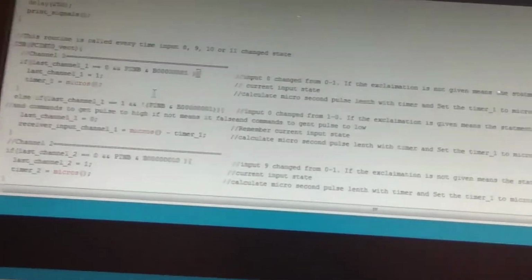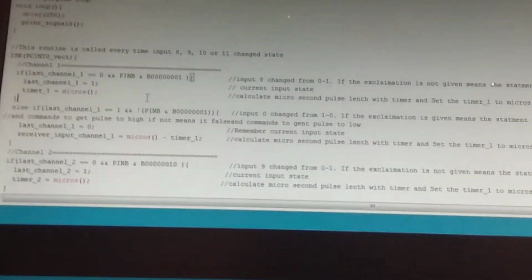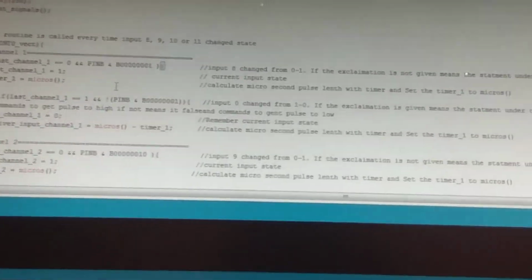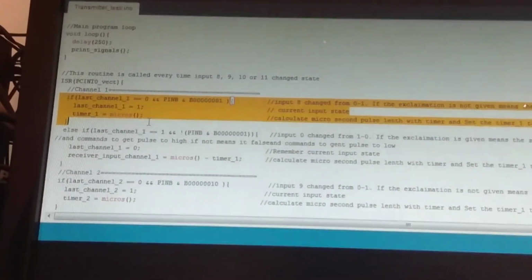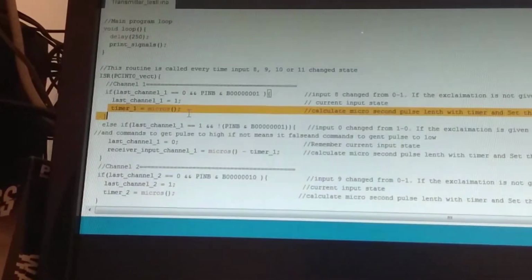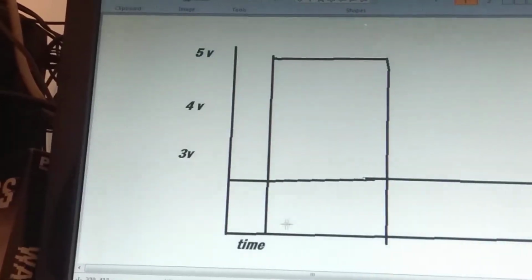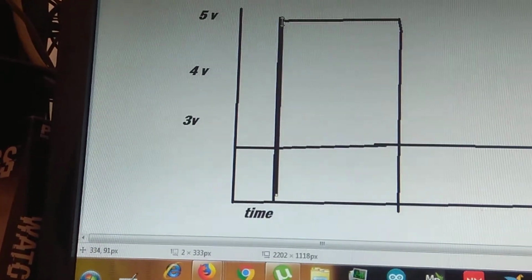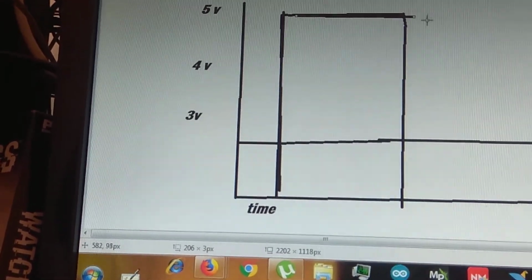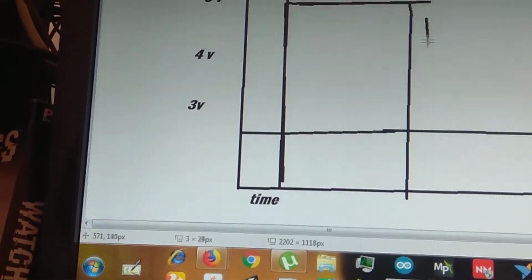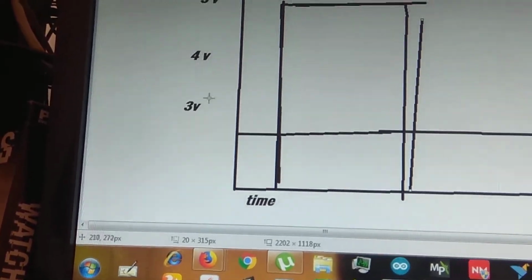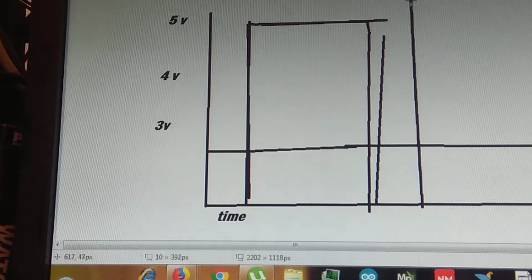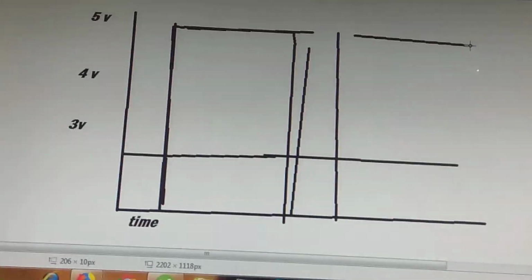Now we cannot wait for the multirotor to receive the commands from the transmitter while doing the flight. We need it very accurate. So for doing that, we have used this set of commands. Timer equals microsecond pulse, which I showed you like this. It is a 1000 microsecond pulse, then constant, then again falls down from 2000 to 1000 microsecond pulse. So this is how it is done, again and again and again.